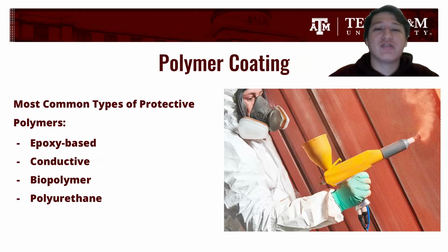They offer an additional defense against corrosion as they are easy to use and can be applied to alloyed steel. These coatings, which can be made from various polymers such as epoxy, polyurethane, and more, create another physical barrier that prevents moisture and corrosive substances from reaching and interacting directly with the metal. By sealing off the underlying material, polymer coatings not only prolong the life of the structure, but also reduce maintenance costs over time because they become an external hull, taking the hit instead of the more expensive metal.